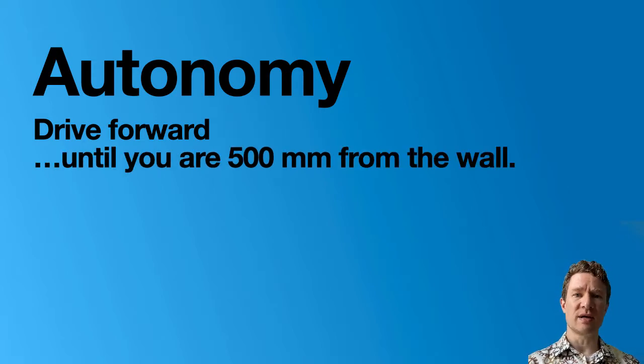So let's take a look at this situation. We can use a whole bunch of different sensors, for example. Let's say we want to drive forward until we are 500 millimeters from the wall, it could be on the floor if we were building a physical robot, or from the wall in VEXcode VR. The reason this is different is that depending on where you are when this part of the program runs, you might have to run a different amount of time or a different amount of distance. So this just says, I don't know where I am, but drive until you, robot, according to your sensors, you are 500 millimeters from the wall.